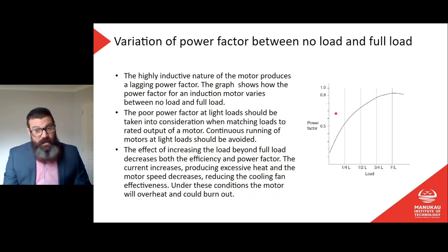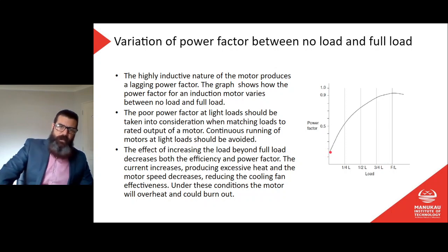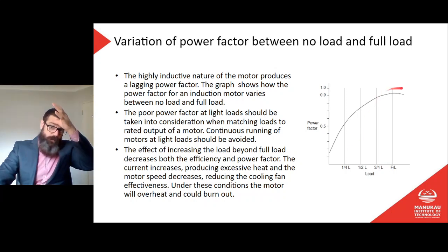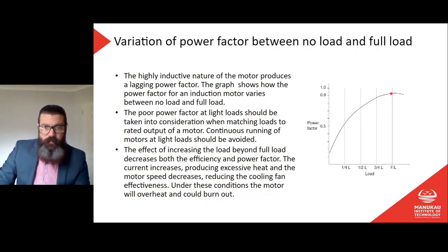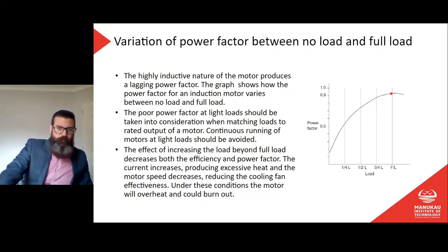So we can see here that at starter, very low loads, our power factor is atrocious. That's like 0.1 or something like that. So it's almost completely lagging. It'd be like almost 90 degrees lagging. As our loading increases, our power factor is going to improve until up here at full load, we're going to have about 90%, or 0.9 power factor.